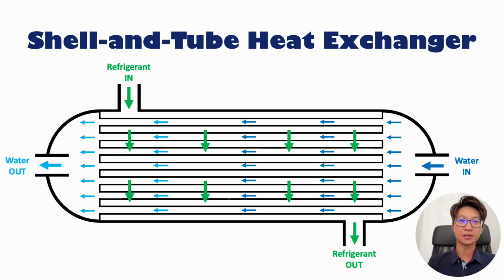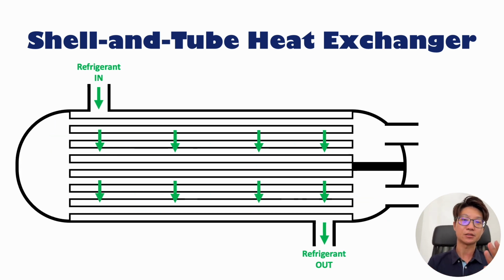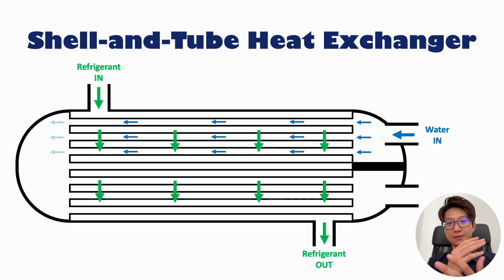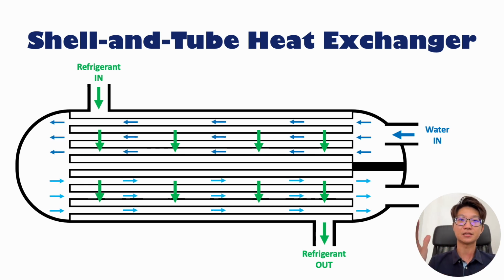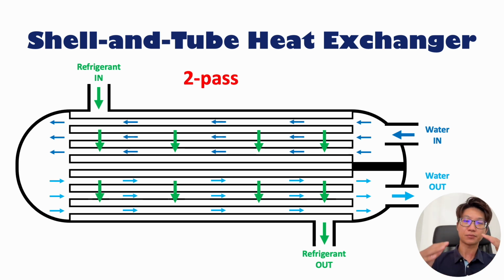chill water already. So the water comes in and passes through this refrigerant one time, then this is called 1 pass. 1 pass chiller, or they call it the evaporator is 1 pass. Now the type is 1 pass type. So there's 2 pass, there's 3 pass also. So let's see, this one is 2 pass. 2 pass means you pass through 2 times. Then the way they orientate it is a U shape, go in and U-turn. For 3 pass it will be like an S shape. But typically most chillers use 2 pass, because between cost and efficiency, most people like to use 2 pass.